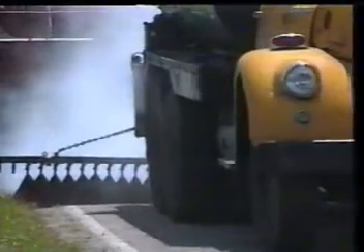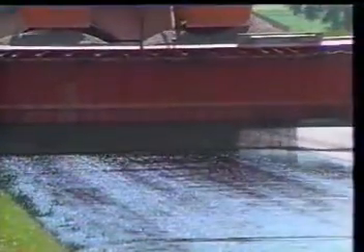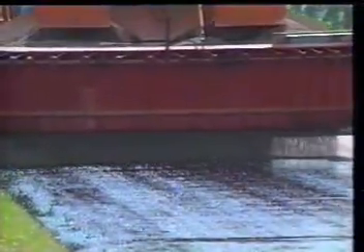The same procedure should be followed when asphalt cements or cutbacks are used, because it's almost always best to run a tight operation. That way there's less chance of traffic driving on the oil. With rare exceptions, the chip spreader should stay within 30 meters of the distributor.